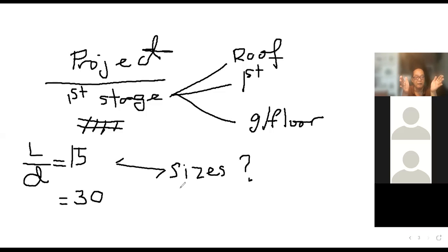What about the width of beams? Then you need to fall back kepada your fire requirement. For a 2-story building, a 1 hour fire protection would be sufficient pada pendapat saya lah. Maybe setengah kata, sir, our group wants to use 1.5 hours, sejam setengah, which is 90 minutes. Okay, it's okay, boleh. So you can choose to use 60 minutes pun boleh, 90 minutes pun boleh. Mungkin saya tanya, why are you using 90 minutes?